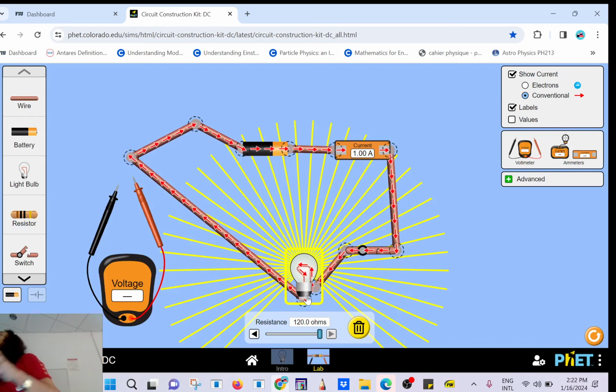Buy those lamps, cheap ones from the dollar store, like the stand here, and you put a 40 and a 100. Of course, the 100 will be the brightest, right? Is the voltage the same from the outlet? Yes, for the 40 watt and the 100 watt. So the voltage is the same. That means if the 100 watt is the brightest, it has more resistance or less resistance? Less resistance.